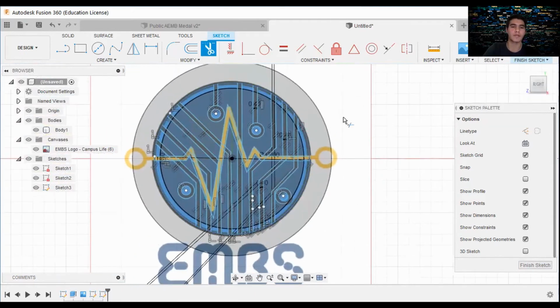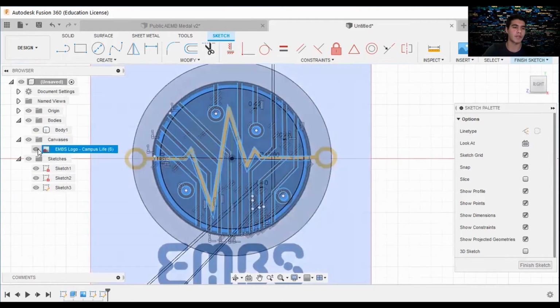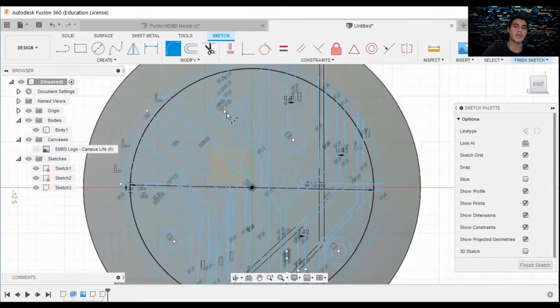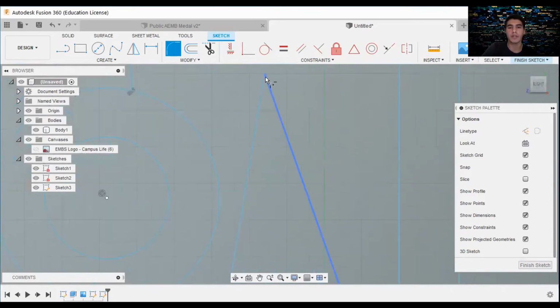All right, guys. So let's see. It looks like everything is done now. We can take off this canvas, and as you can see, because of the canvas, what we have is a sketch. That's all we have left, and that's good because what we're gonna do is extrude this. So when you have the time, you can go to the sketch and click fillet. You see these sharp edges? If you want to make the sharp edge rounded, then you just go ahead and click fillet.